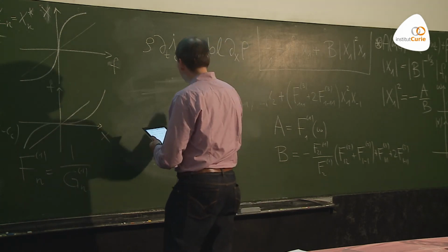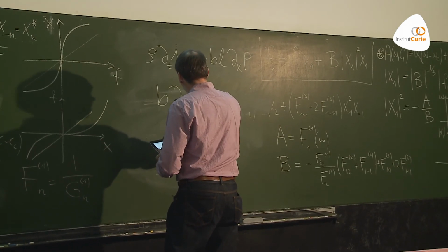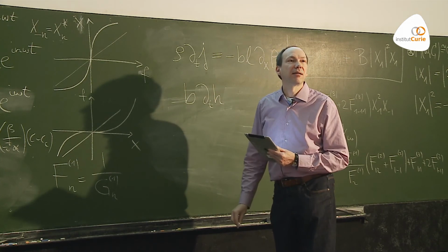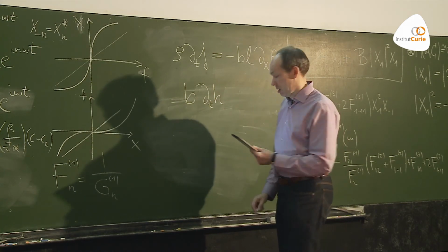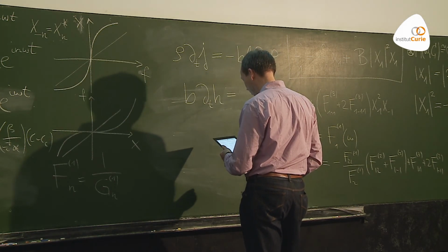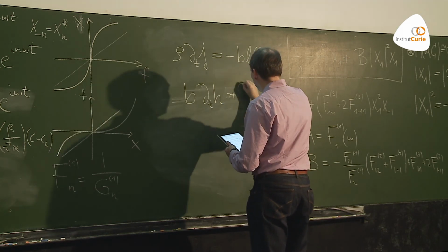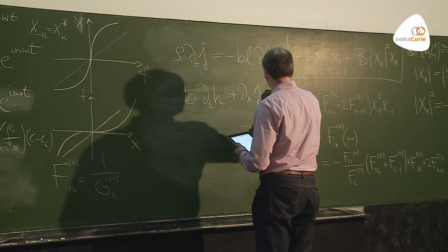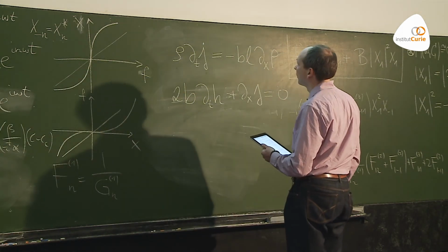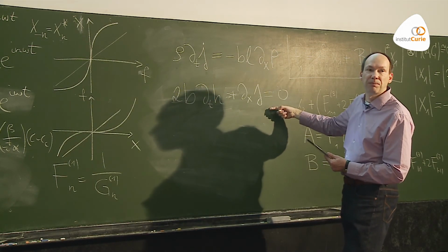So the second equation is that the width of the channel B times the rate of change of the height, that's something like volume that is displaced locally by height change. And this then has to be balanced by a flow. So there has to be a flow, otherwise it's not possible because the fluid is incompressible, plus d_x j equals 0. And if you do it for the two chambers, you get a factor of 2 here. So we have a force balance in the fluid, and we have a conservation law.